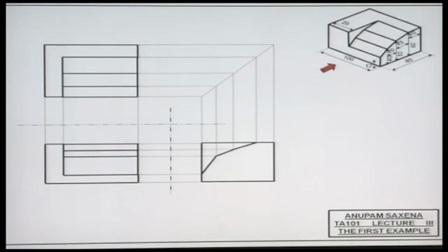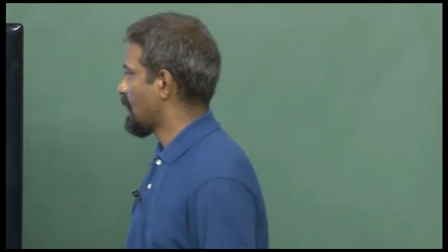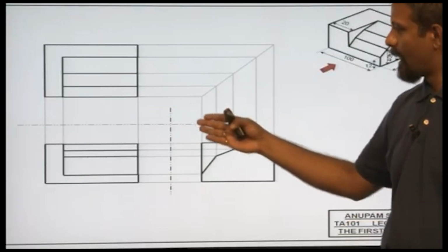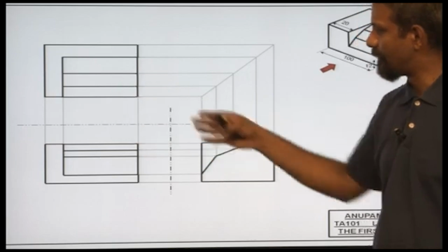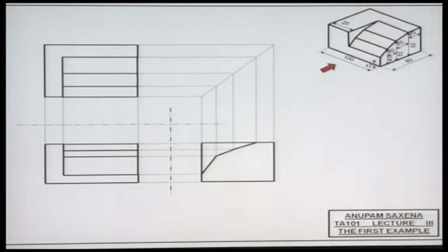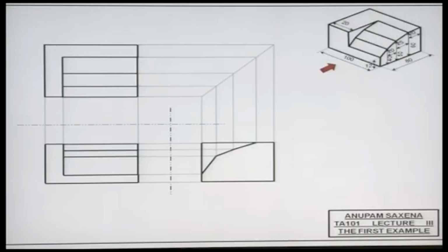You know, there are a lot of chances that you're going to be making mistakes when you're working with these technical drawings. So these projection lines are going to be helping you out in identifying those mistakes. So if you're missing any feature in any one of these views, after you have drawn these projection lines, you will know for sure what you have missed. So you've got to be very careful and sketch, sketch, sketch. Practice and keep practicing. This is what the golden rule in technical drawing is.